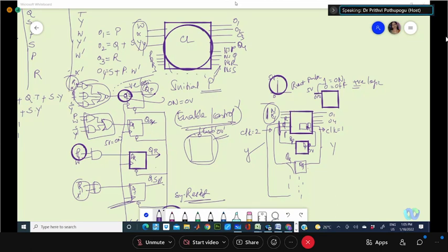If the sensor placed inside takes an obstruction, it will take it as a down count. So you are using an up down counter circuit, which will have the sensor outputs controlling the up and down direction.